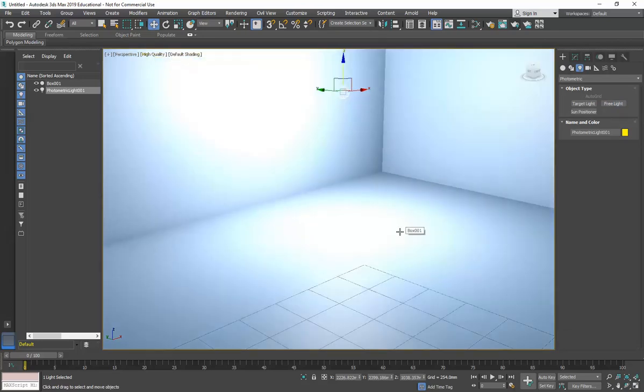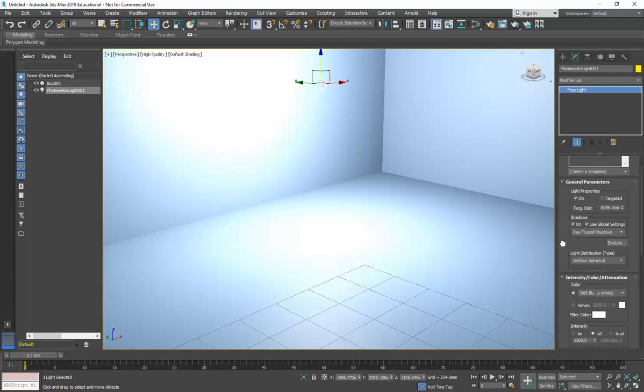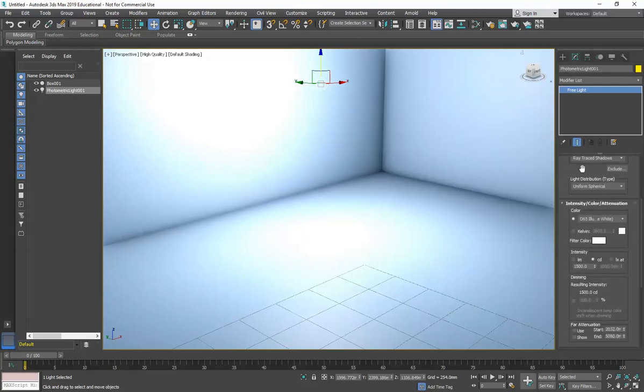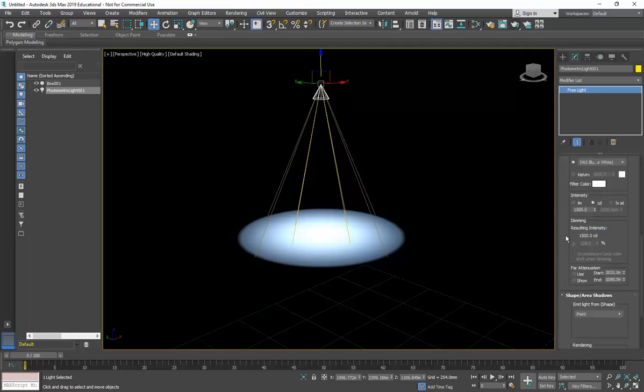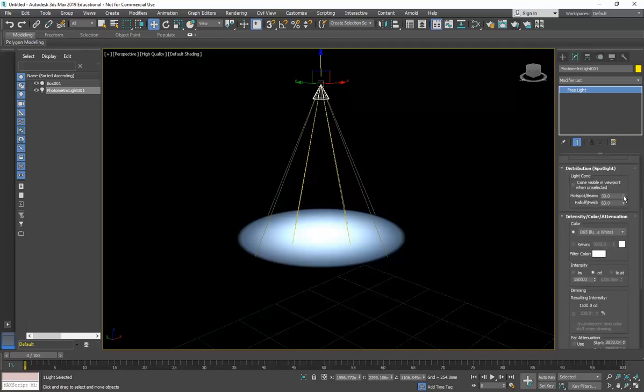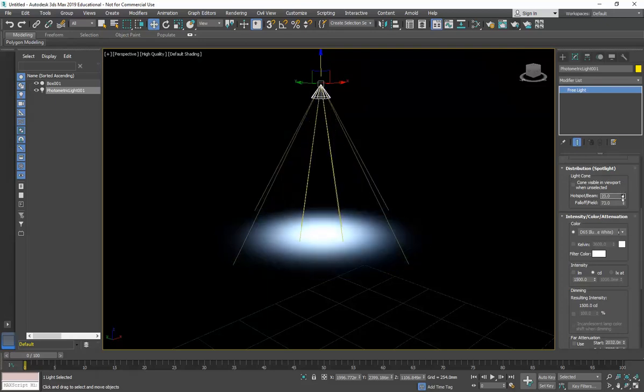There we are. That's normally something you can do without that much trouble in 3ds Max, but again, things that come from Revit sometimes have a bit too much other stuff going on, and it overloads the hardware, and these poor old computers, even though they were good when we bought them, are probably a little bit past it for this sort of work. So now if I look at that light and find the same settings, I'll get the spotlight distribution, and now here we go. Then you can really clearly see the hotspot and beam working together.